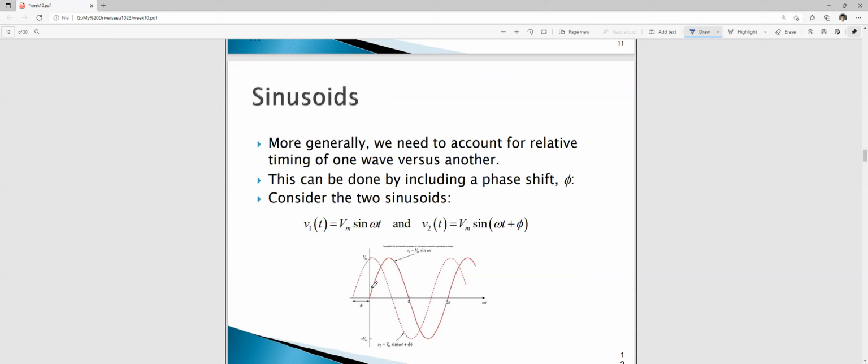Okay, so this is the original waveform, which is V1 here, a sinusoidal waveform with the expression Vm sine omega t. The second waveform here is leading V1 by some degrees, which is 5 degrees. Since this voltage is leading V1, we put positive. The value of how big the difference is, this is phi, the angle difference between V2 and V1.